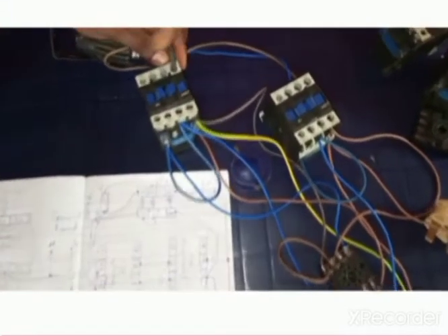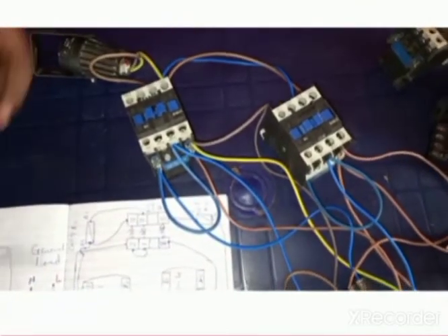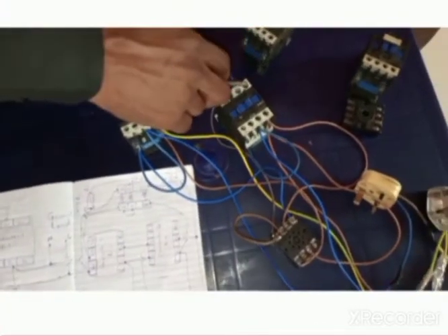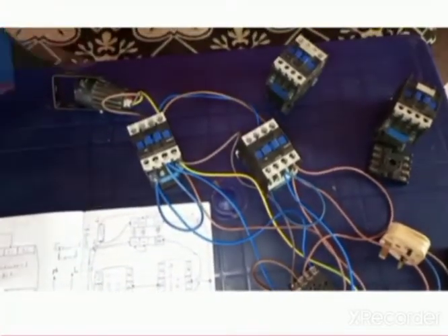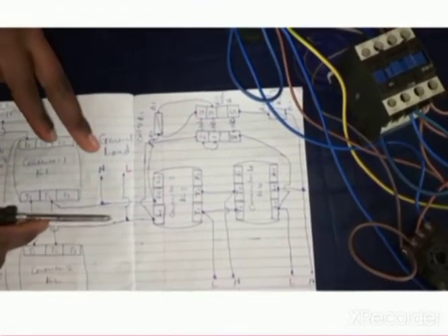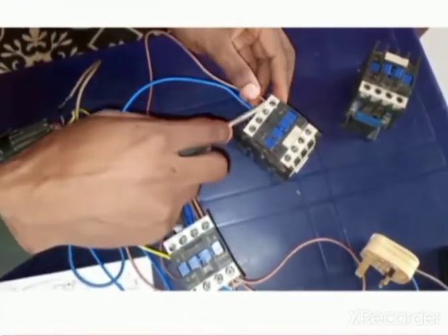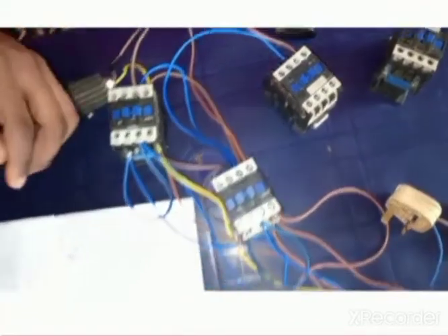So after connecting it to T1 and T2 of this contactor now, you see that another thing is that the T1 and T2 of these two contactors, you can take it from any one, goes to where L1 and L2 of contactor 3. So I'm using this as contactor 3. So I'm connecting T1 and T2 of this contactor to contactor 3. When you look again, you see that we have connected this T1 and T2 to L1 and L2 of the third contactor, which is this contactor 3 here.